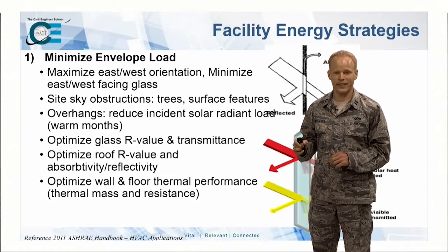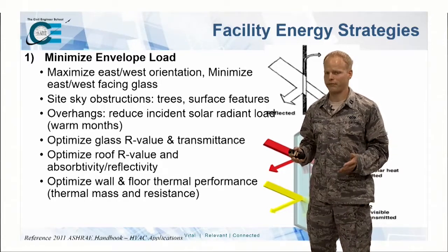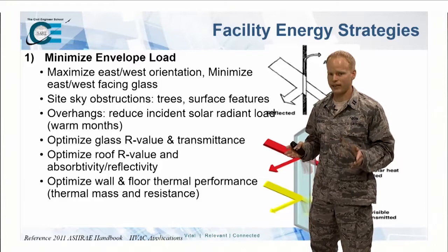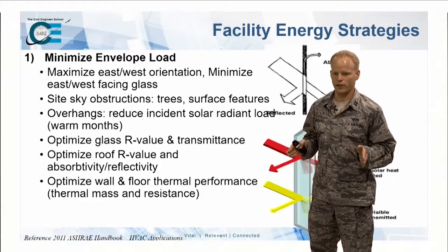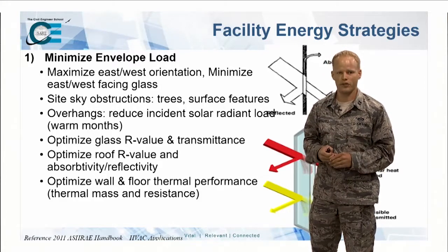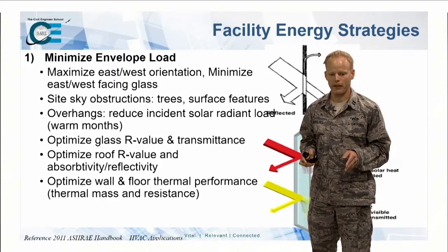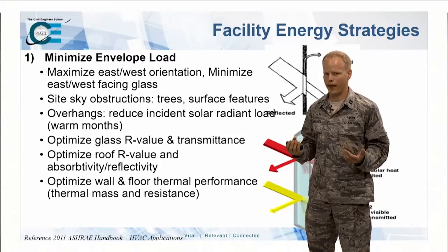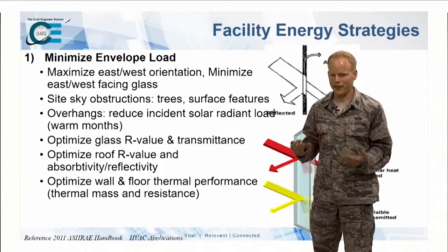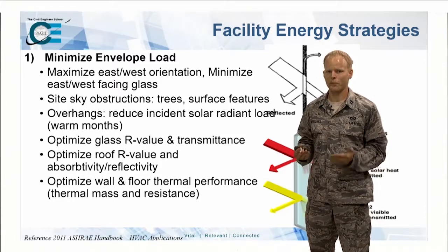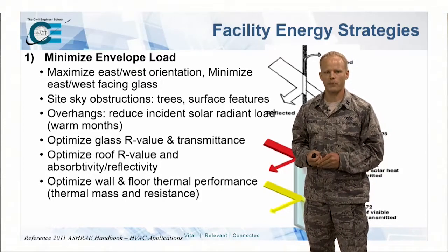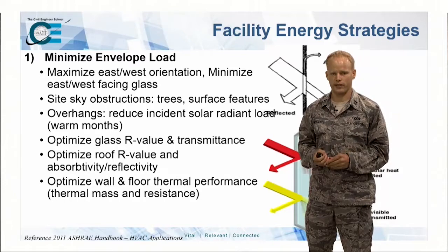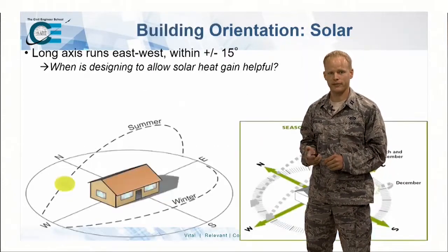And one of the biggest loads, I went through and did a study on AFIT for another lesson, is heat. I was looking at two different materials on the west side of the building and how fast they were heating up. The dark one was heating up faster than the light one. We all kind of know that, but we don't really think about that all the time with our buildings. Simple things you can do. And then optimize wall and floor thermal performance, thermal mass and resistance. I'll talk about each of these.